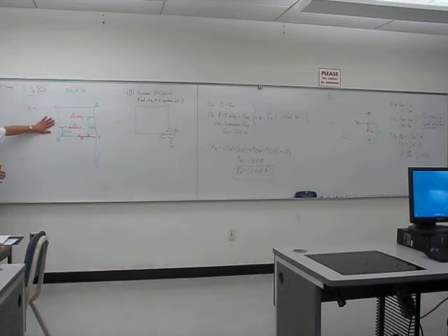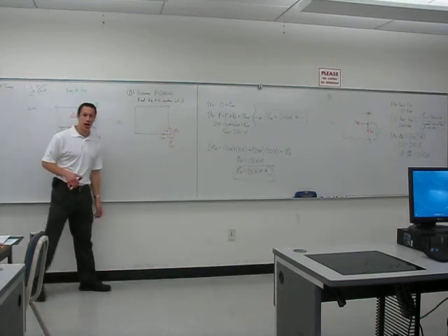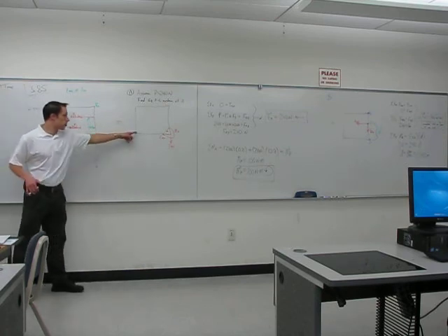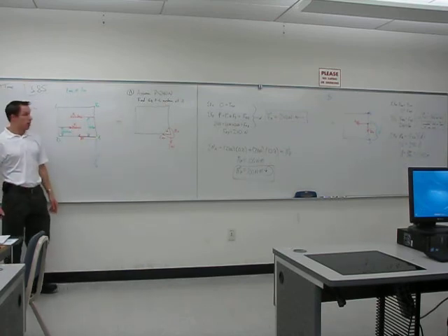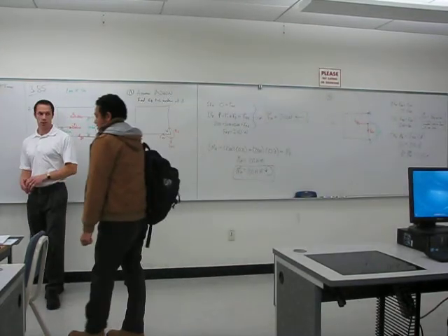Okay, so we started off with a box that had 3 people pushing 3 different forces. We reduced that to a single force and a single moment applied at the point A, and this box will behave exactly the same as this one. Remember, this moment vector that we have here represents a force couple.